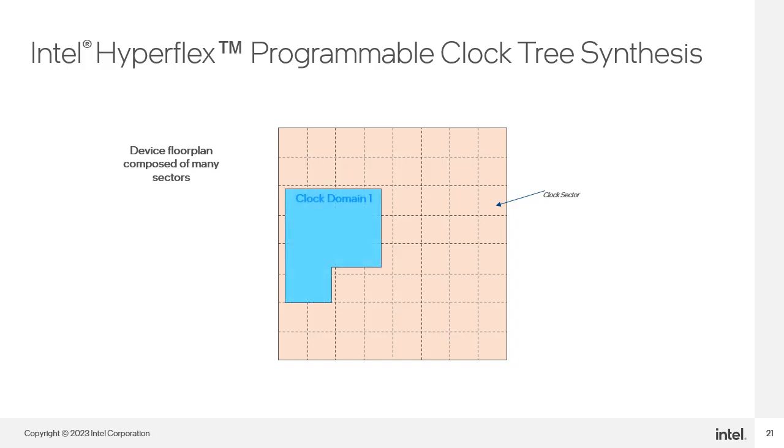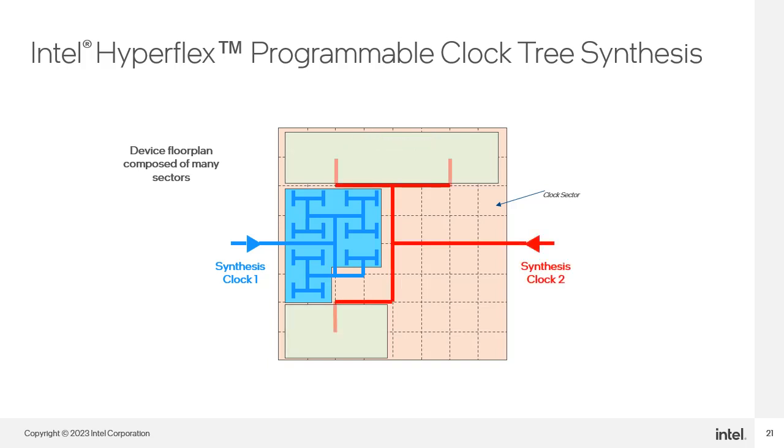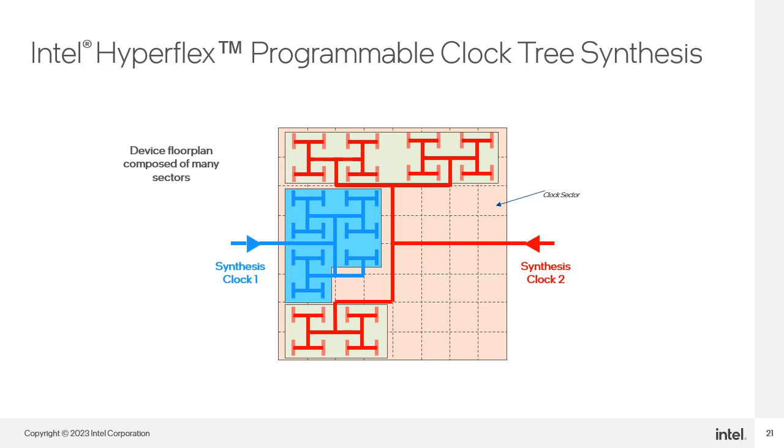sector. For clocking the first module, instead of using an entire global or two regional clocks, the clock tree segments are synthesized to encompass only the area that is needed for that module. Again, for the second module, the clock tree can be synthesized to drive only the necessary logic. Even though the fitter may rarely split a clock domain in this way, it is not a problem to synthesize the clock tree as needed to drive those registers.